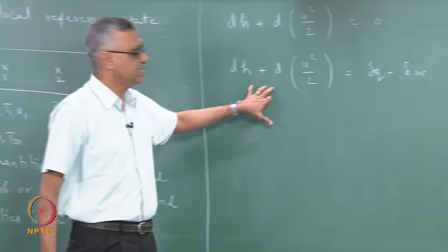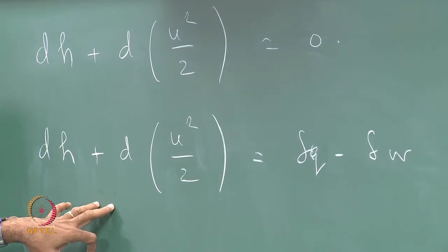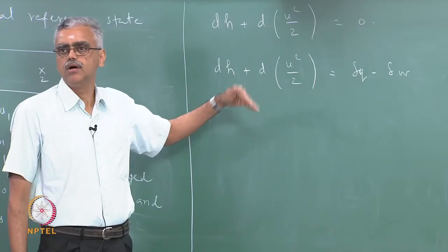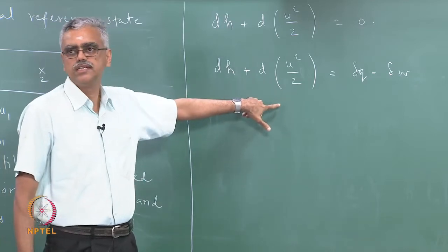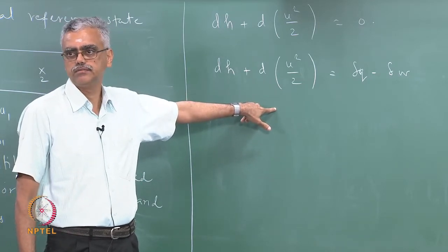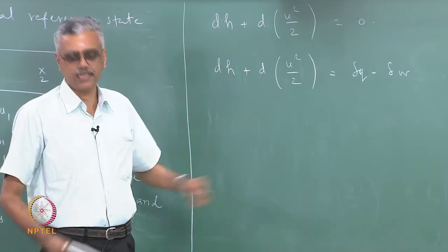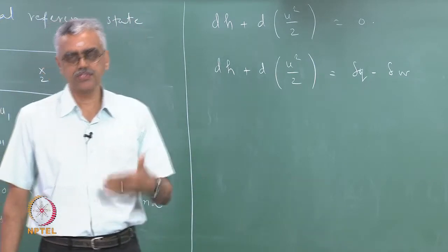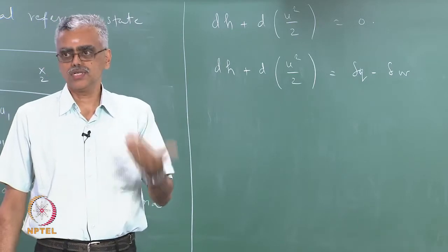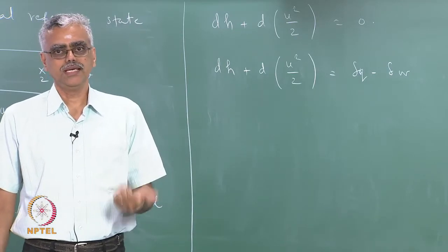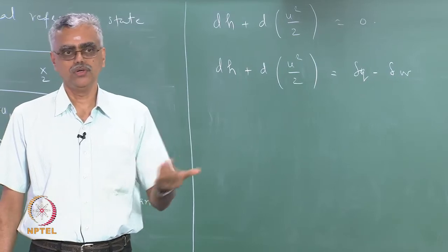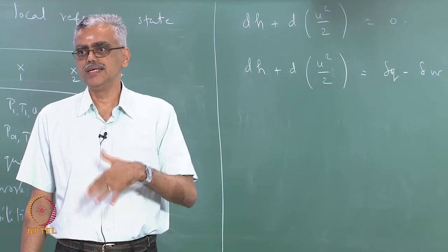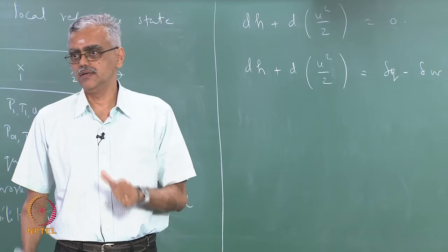So, you can see that stagnation temperature can be changed by giving heat to the system or having a heat interaction with the system or having a work interaction with the system. So, when I do either one of these, the stagnation temperature will change. Okay. Next, we need to look at stagnation pressure. For example, if I add heat to the system, then the stagnation temperature will increase. Or across a compressor where work is being done on the system, again stagnation temperature will increase proportional to work, and across a turbine where work is extracted, stagnation temperature will decrease because we are extracting energy from the turbine.